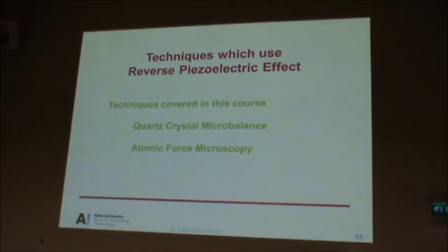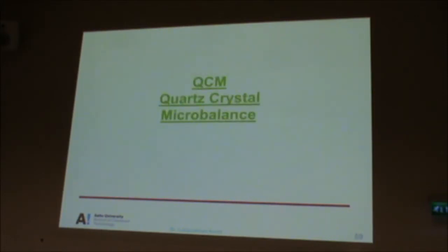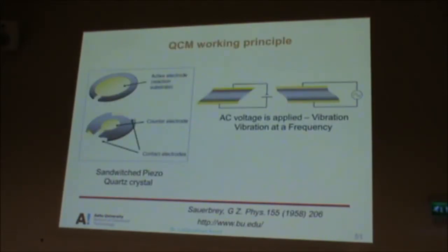You control the vibration. Here are the techniques that you will be learning in this course that use the piezoelectric effect as the basis of measurement. One is the quartz crystal microbalance, the other is atomic force microscopy. I'll start with the quartz crystal microbalance. Here we have a piezoelectric material, which is a quartz crystal, sandwiched between two electrodes. This is the upper side of the electrode and this is the lower side. Usually this electrode is gold.